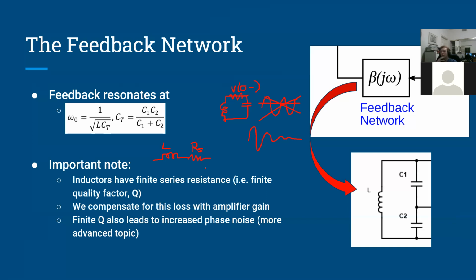So what we hope to do here is use the amplifier to sustain that oscillation at one particular frequency, which is the frequency that this tank oscillates at. Okay, so we're compensating for the loss with the amplifier gain.